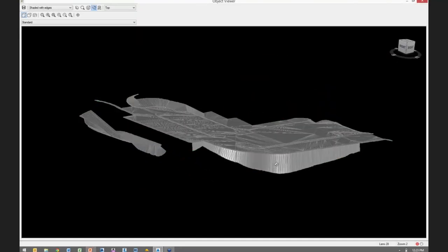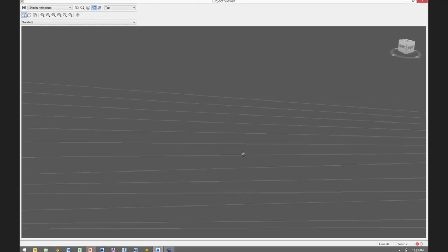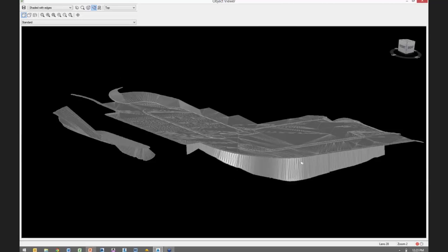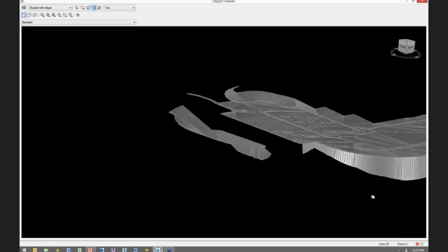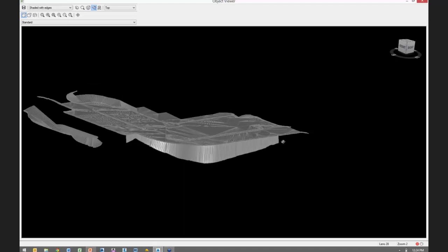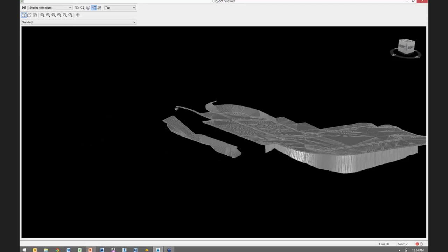Okay, so we're putting a retaining wall on this back side here, and we're daylighting right into existing. A lot of different ways to handle grading or retaining walls. This is just one example of them. So now what we're going to do outside of this retaining wall is put a daylight grading over on this end right here. And then we're going to run a transition between that retaining wall and that daylight grading. In this case, we probably would need to run the retaining wall a little further, but for this illustration, it's going to work fine.